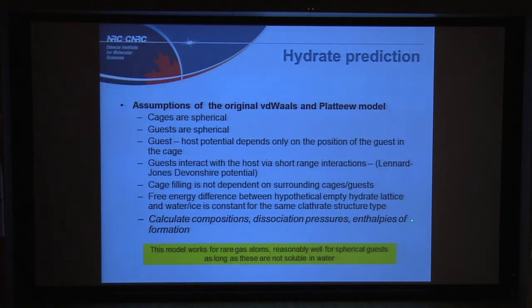And then what one can do is calculate compositions, dissociation pressures, enthalpies of formation. So one can use the van der Waals model to predict hydrate formation conditions and a number of different hydrate properties. And as van der Waals already pointed out, this model works for rare gas atoms reasonably well, for spherical guests, as long as these are not soluble in water.